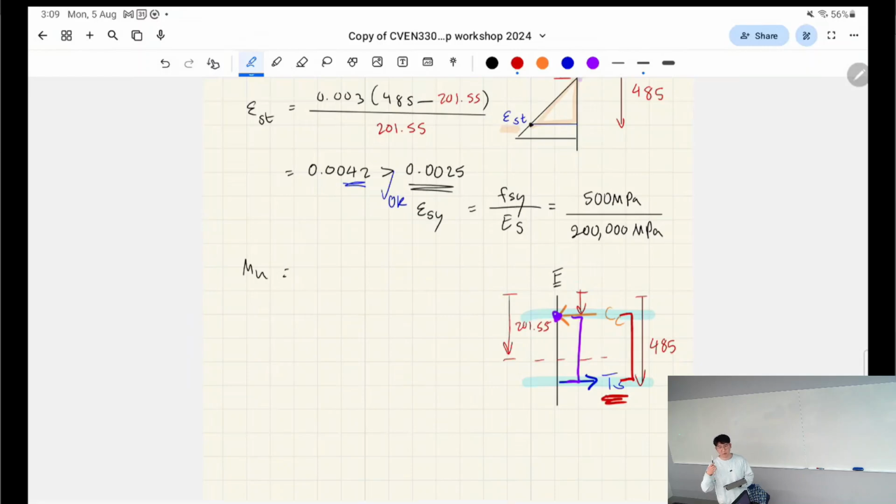This is actually where flexural design steps come from. So as you're looking through the flexural design steps when you're studying, this is how they can find out the forces of the concrete without necessarily knowing how much steel will be in the concrete. They can take the sum of the forces here and ignore how much AST we need. Right. So this is a very common method that they utilize.